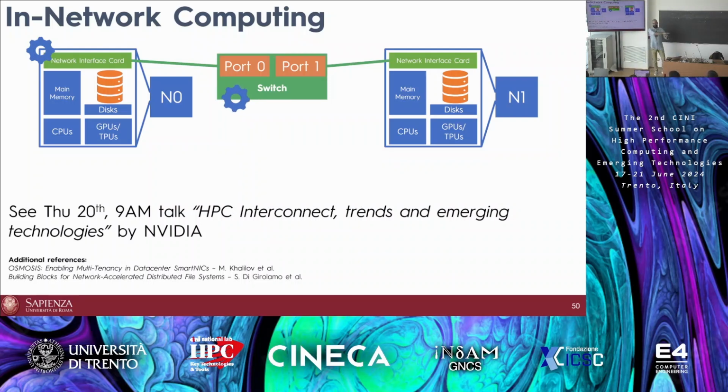So I'm doing this big digression, but anyway, we have time. They have this kind of ASIC, which is basically a pipeline. It's just a bunch of compute units. You have a block here, then another block here, and so on. The packet goes through this pipeline, and in each stage you can only do a fixed amount of operations. That's super complicated. It means that you cannot have loops. You might have them with some nasty tricks, but it's going to drop performance. You cannot do many things that you would do normally with a computing architecture, so it's very limited.